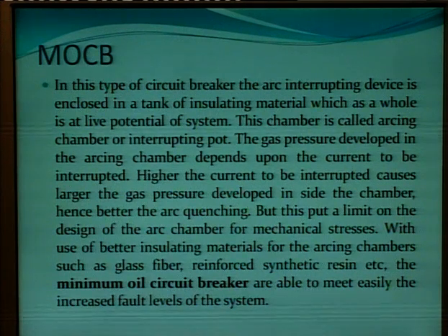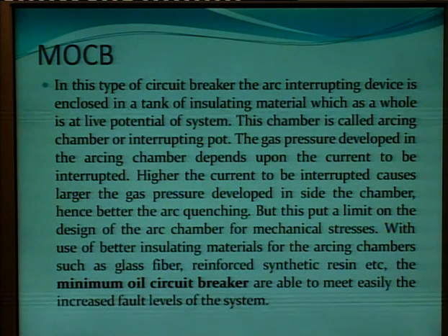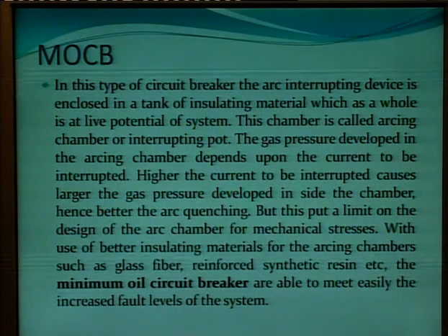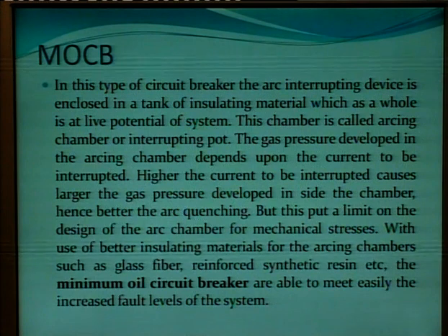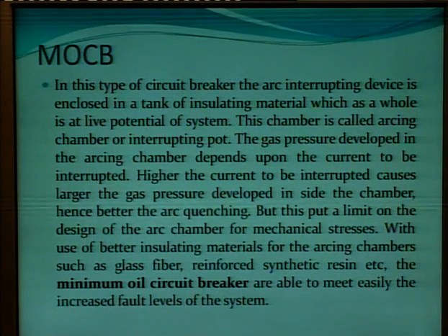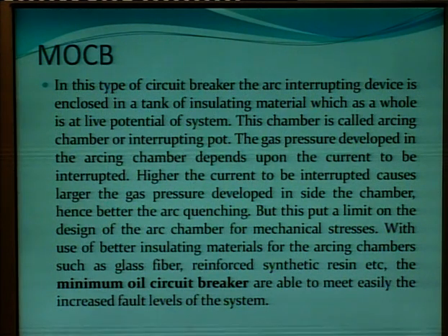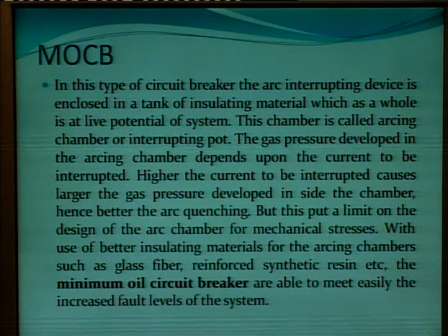But this puts a limit on the design of the arc chamber for mechanical stresses. Now with the use of better insulating materials for the arcing chambers such as glass fiber, reinforced synthetic resin, etc., the minimum oil circuit breakers are able to meet easily the increased fault levels of the system.